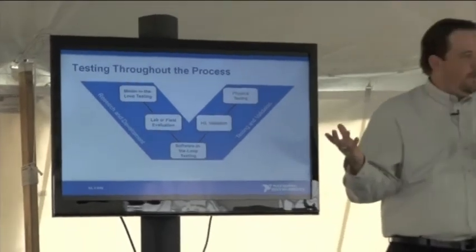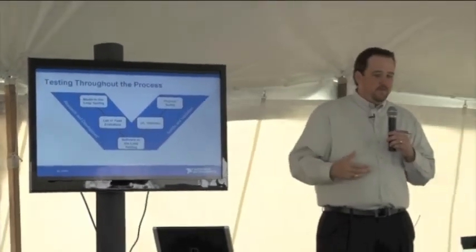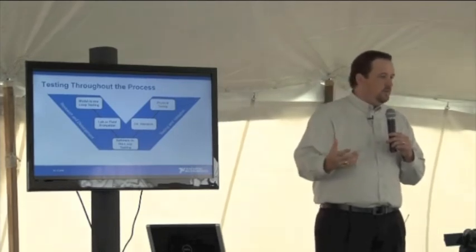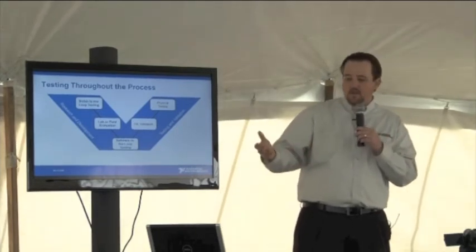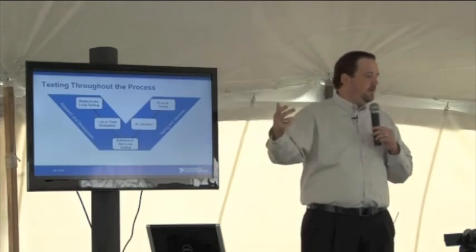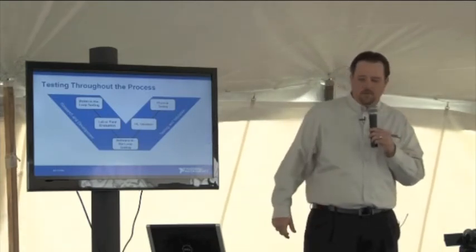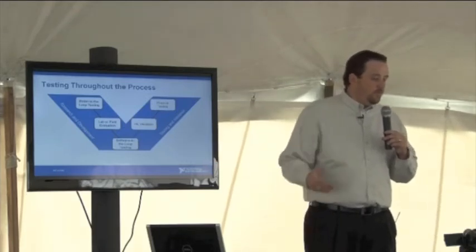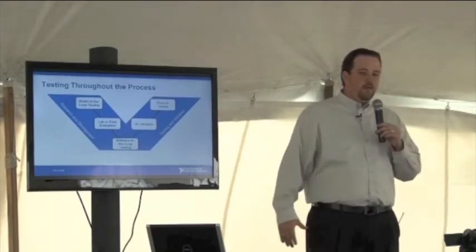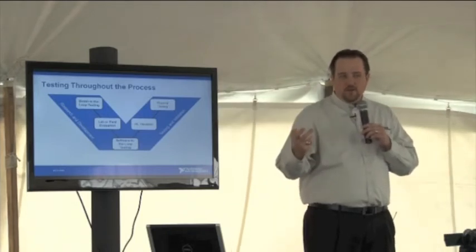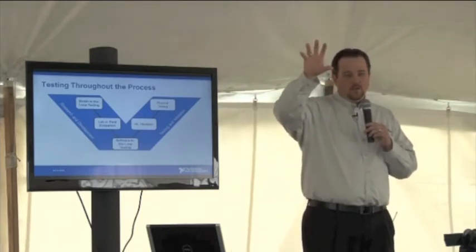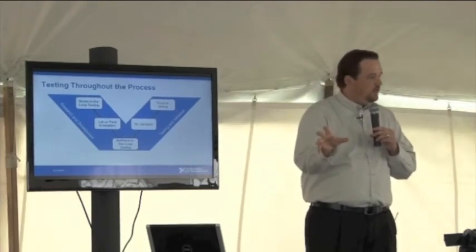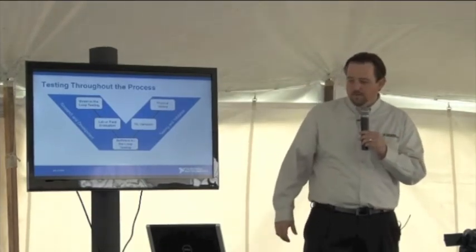And really that prototyping, when you build that prototype, well, that was typically thought of as the design phase of prototyping the controller, but really you have to test that prototype, and so you need a test cell or a hardware-in-the-loop simulator here to perform that evaluation of your prototype. And then at the bottom there's a technique commonly used and more frequently being used called software-in-the-loop testing. So here you look for errors in translation from model-based equations for control to C code or actual machine code that's being used to implement that on your hardware.